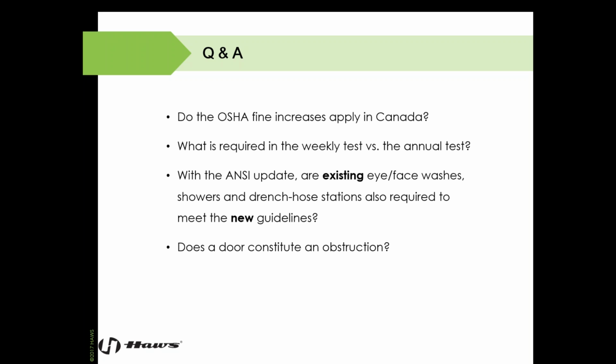What is the required weekly test versus the annual test? We touched on that. In the standard, it is bare minimum. The weekly test only requires you ensuring that water hits the heads of both the units, the shower and the eye face wash, and then ensuring that you clear the dead leg, however long that duration may require. The annual test is everything else we went through. All of that needs to be checked on an annual basis. If there's any other questions with that, feel free to reach out to us. And again, we have Zavato and the training program, the on-site inspection program that can help you with that if you're still in question.